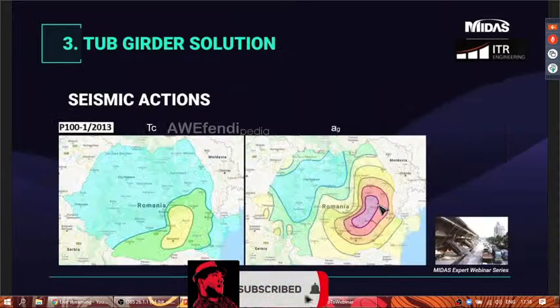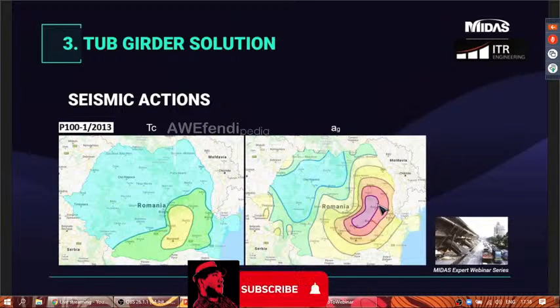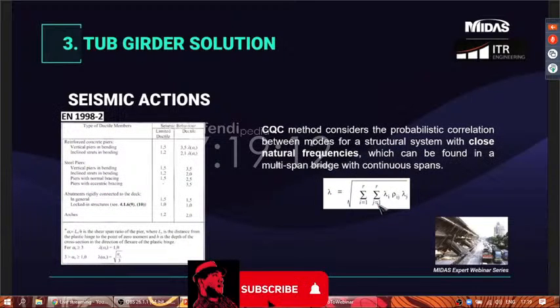In this phase, the substructure has been modeled in MIDAS, and the effect of the seism has been analyzed. The Romanian code P100 that is included in the program provides some maps to identify the location where the structure is and to obtain the values of the corner period TC and the acceleration of ground level AG. Knowing these two parameters, we have almost all ingredients to execute a response spectrum analysis.